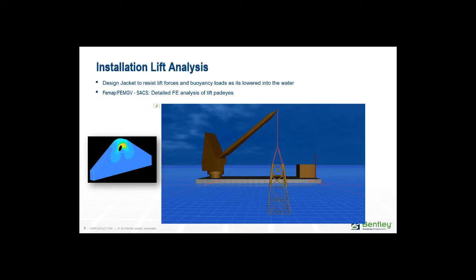For the installation lift analysis, the jacket is designed to resist lift forces and buoyancy loads as it's lowered into the water. We have interfaces to general purpose finite element meshing packages such as FEMAP and FEMGV, which can be used to do a detailed finite element analysis of the lift pad eyes.